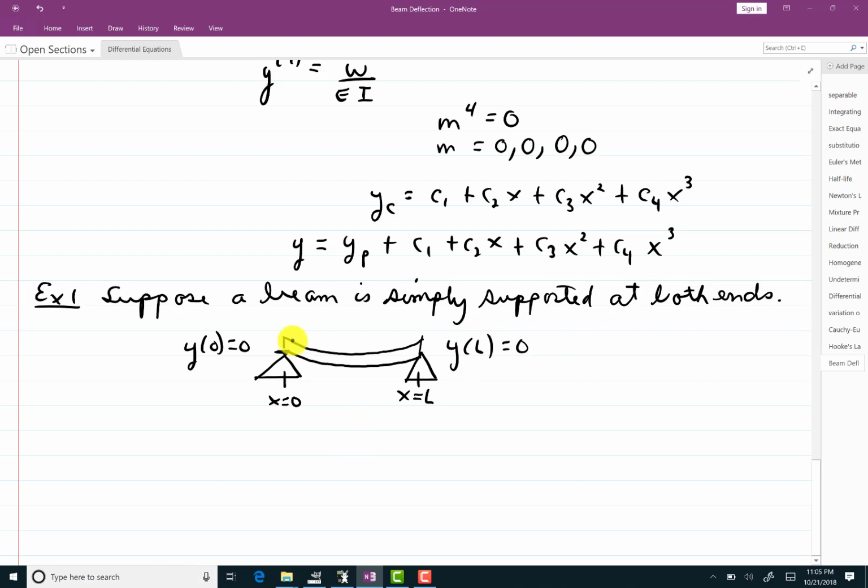Now, other than that, if you look, this is pretty flat near the end here. So whenever you have flatness like this, that means the slope here is fairly constant. But better than that, we have that y double prime of 0 is 0, and y double prime of L equals 0. Because of this flatness here, the second derivative will be 0.